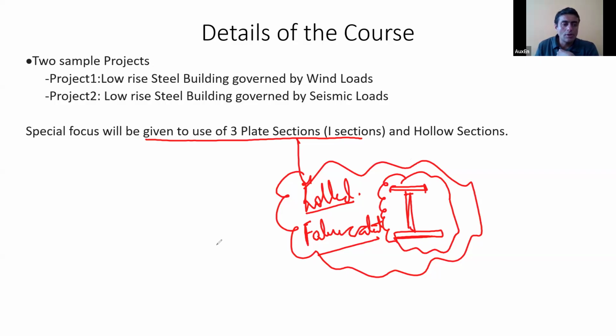Yes. So you can say, first of all, rolled sections will have some limitation. All of us know that they will have standard sizes. So if you talk in terms of the ISMBs, Indian standard sections, the largest ISMB you get is ISMB 600. You cannot get more than that. And in the rolled sections, the section dimensions are such that they are quite stocky sections.